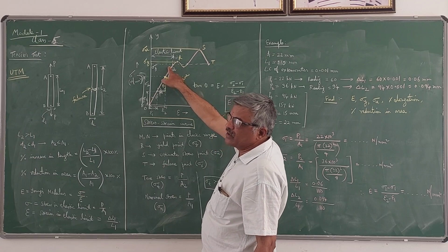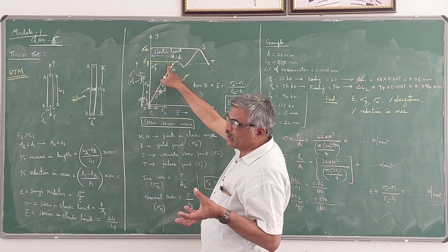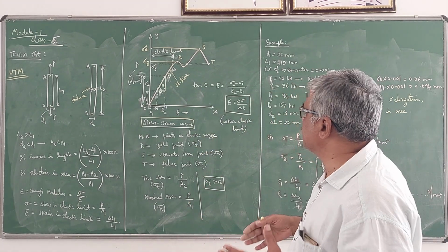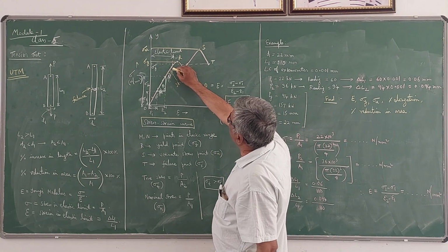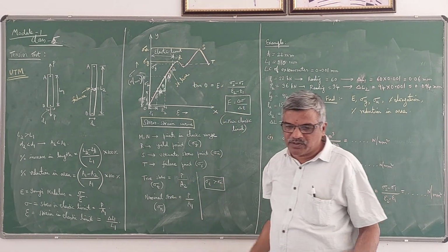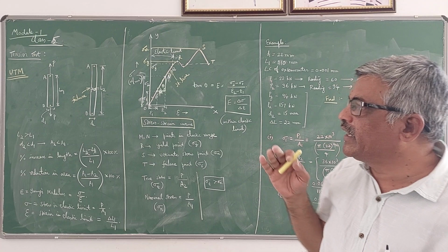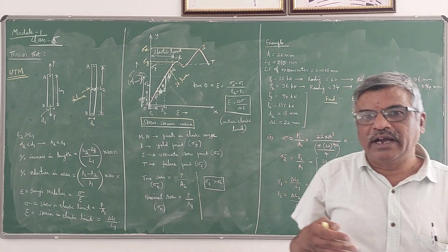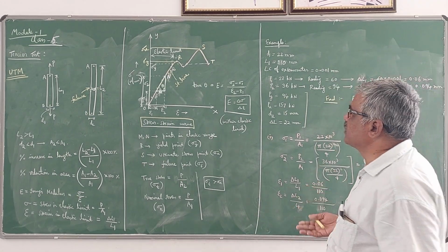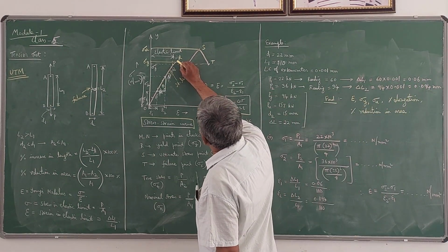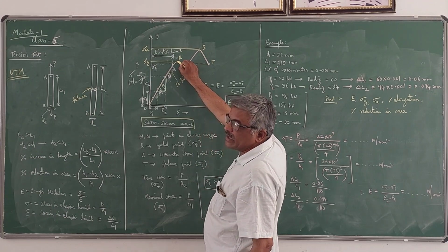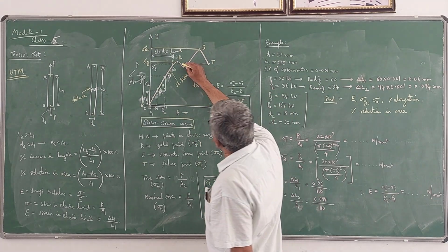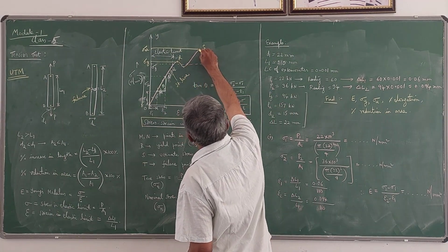Up to this, if you remove the load, the specimen regains its original length and diameter. Then afterwards it enters the plastic state. So the elastic state is over there. Then it starts getting permanent deformation, so that even if you remove the load, it won't come back to its original length and diameter. If you take a point here, R, that point is called the yield point. The material starts yielding there, then the stress slightly reduces, then once again increases rapidly.